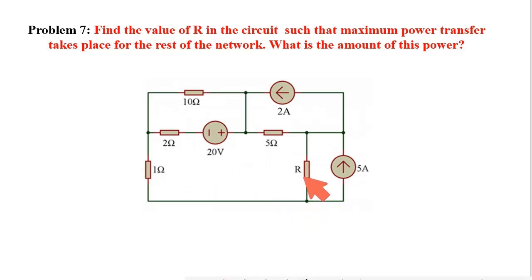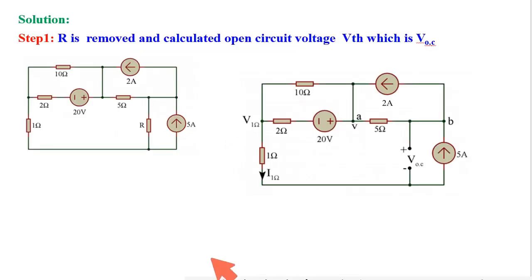Problem 7. I need to calculate the value of load resistance to get maximum power at load. I also need to find that maximum power. I am following the maximum power transfer theorem. First, I need to find the open circuit voltage.